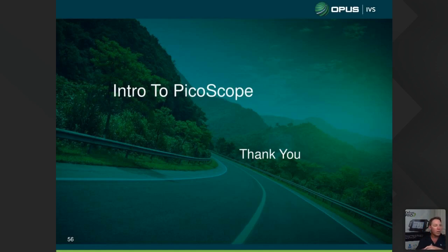And the reason we use a scope to measure what's actually happening in an actuator is because we see it in real time and we see what's actually happening down at the pointy end. I know we can look at a scan tool and go, yep, open EGR, and we rely on the feedback from the EGR to tell the scan tool how many % open it is. Sometimes we know that's not true because the position sensors can fail inside there or not read properly, and that's why we're triggering a fault code. So the idea of the scope, it rules out the feedback option. We just read what's actually happening down at the sensor, and we're not getting any modification from the control unit itself before it gets to the scan tool. But that's what we're going to cover next week.